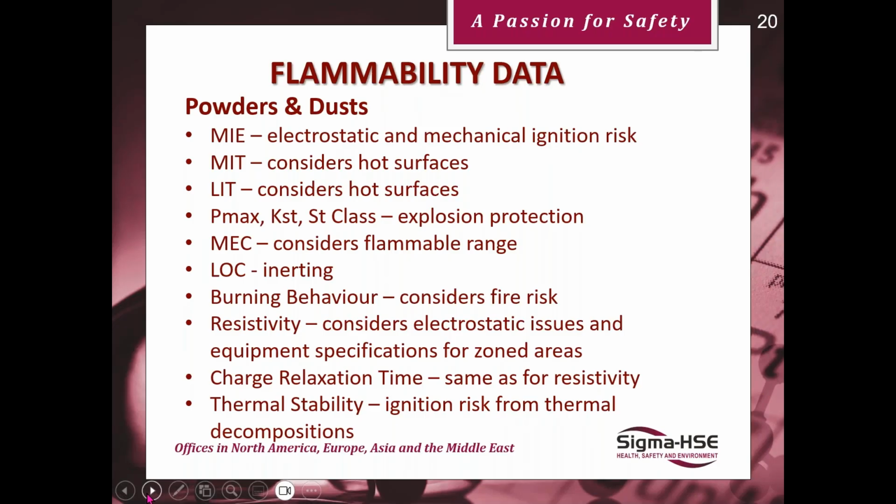Limiting oxygen concentration is what you'll need as you consider inerting for explosion prevention. A lot of people don't bother with burning behavior, but I've had some pretty fast powders in the past. For transportation, it's necessary, and this determines how fast a material can burn, in other words, the fire risk.